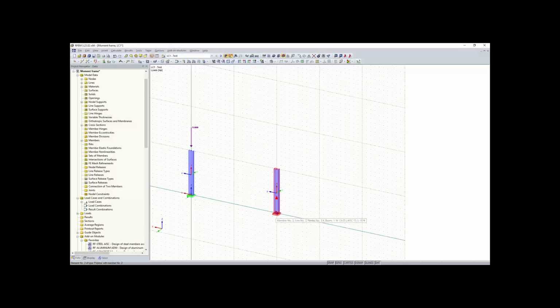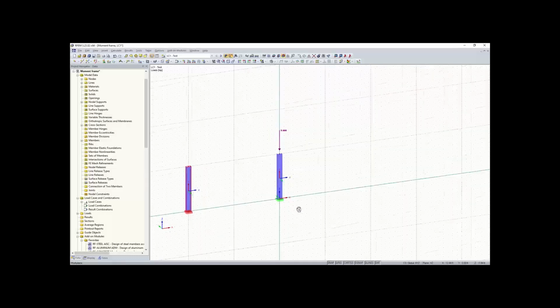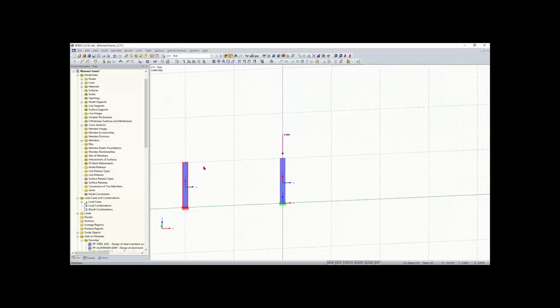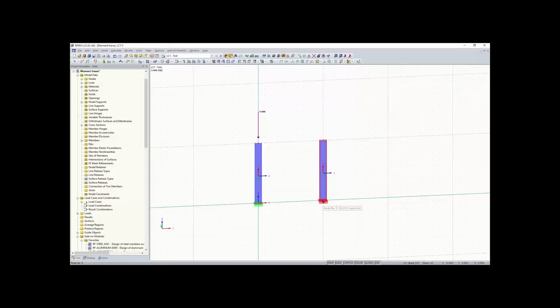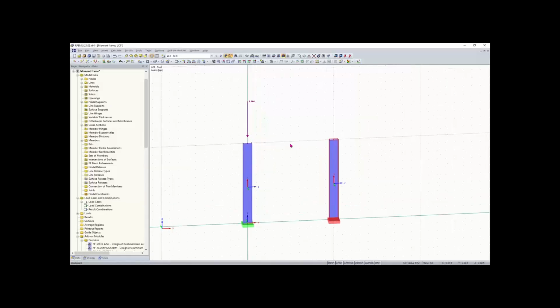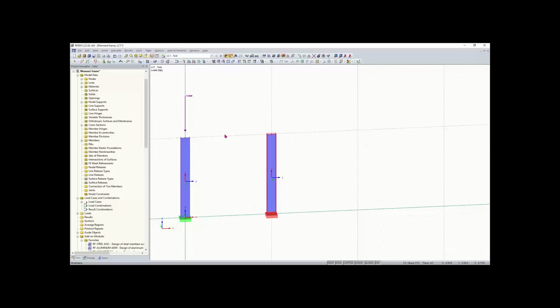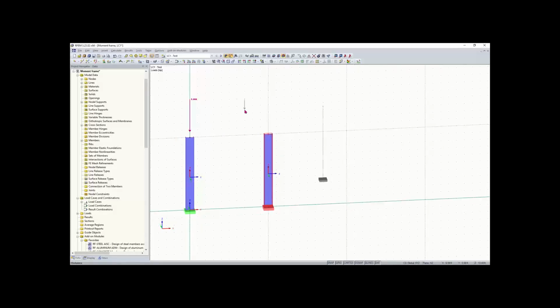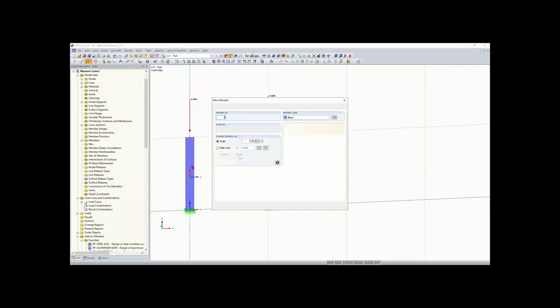I want to make that 10 feet in the negative x direction, or actually, I want to make that in the positive x direction, and it's going to be 10 feet away. And then what we can do is create a beam spanning between our columns here. I can also just hold Control and... I can Control Z to undo that. What I can do is just hold Control and move this loading over. And now I can draw a beam that will span between the two columns.